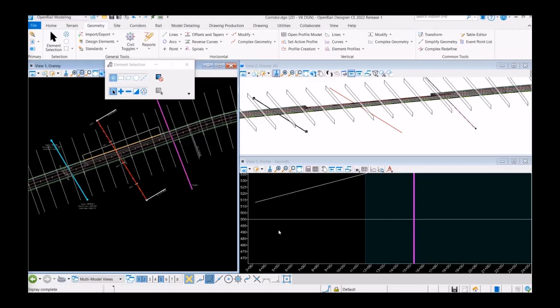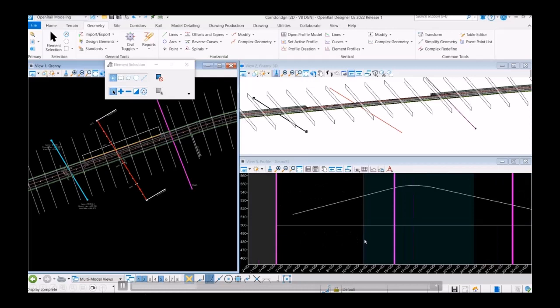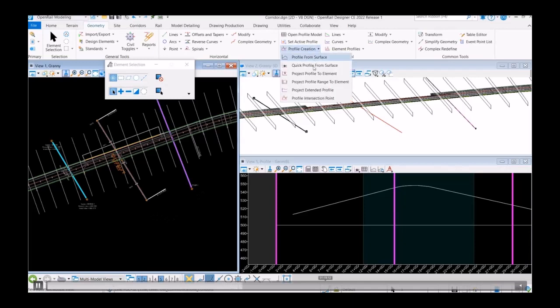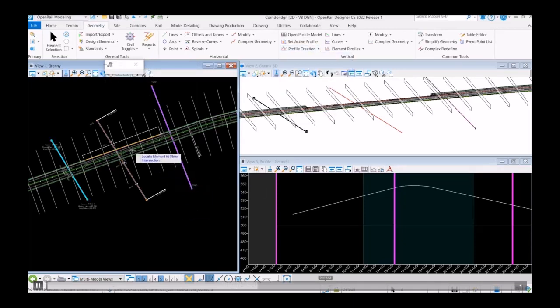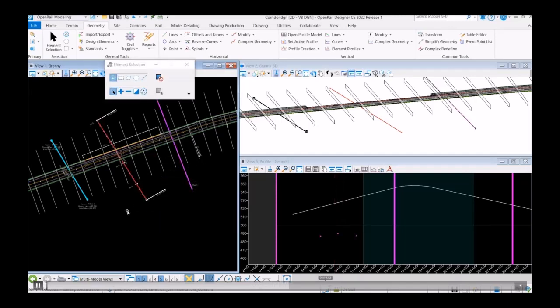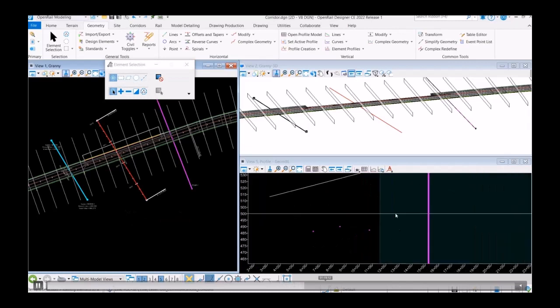Okay. So basically what this does here is, you can see here I've got 3 elements that cross. I think one's a conduit, one's a baseline, one's a pipe. And then what you can do is you can do those one at a time, which is the way that it worked in the past. But now you can actually put them all into a selection set. When you identify the selection set, you can put all 3 points in there at the same time. And so that's the advantage here, and it'll recognize if there's a selection set and place those points in there correctly.